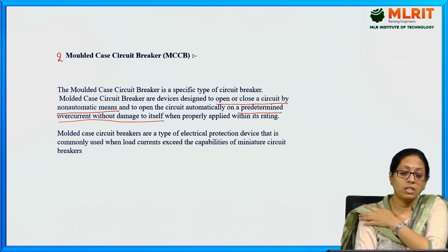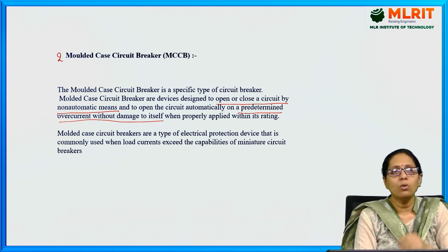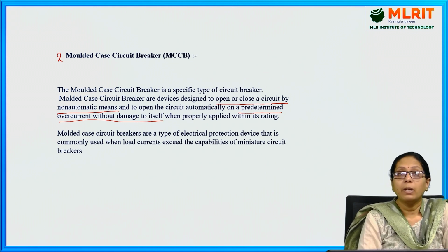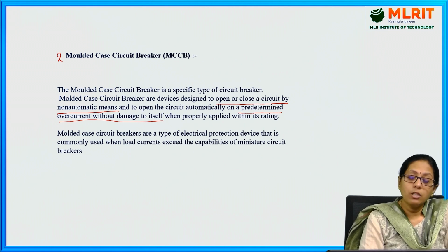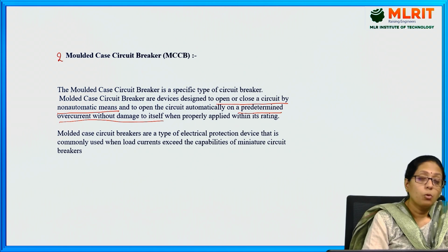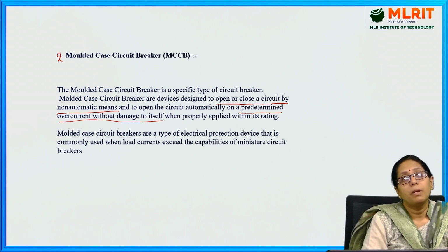That means based on the predetermined current value, it will automatically open without damaging, and it can be used non-automatically also. So both ways the molded case circuit breaker can be used, automatically as well as